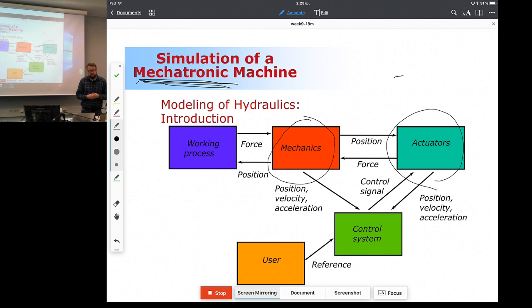So you typically need to use ceramics or something else that is quite expensive. That's a little bit of a problem in water hydraulics. Another problem is that if you leave water in a container, say I leave water in this cap for 2 months, and then I come back, the water is no longer water, but a creamy liquid that grows monsters.